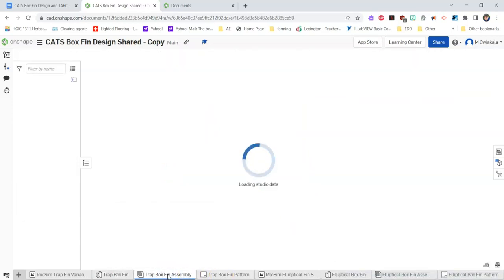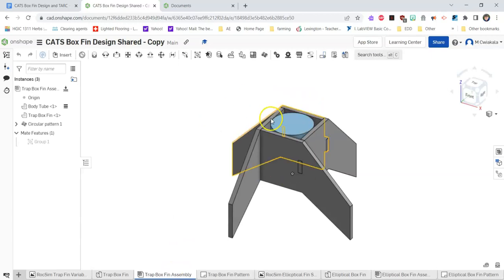which shows all fins wrapped around a cylinder that is the body tube that you've specified. So this fin arrangement, the fins are mounted on the outside. The little tabs and holes have been provided so that the fins can lock in, making the assembly process a little bit easier. If you're doing these by hand, you could simply ignore cutting out the square holes in the straight and then just glue them on that way.